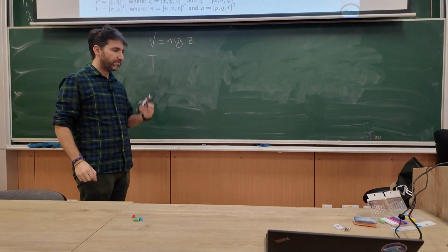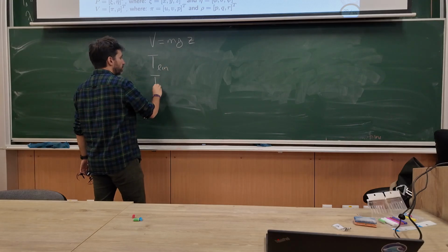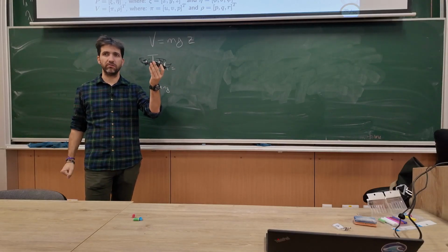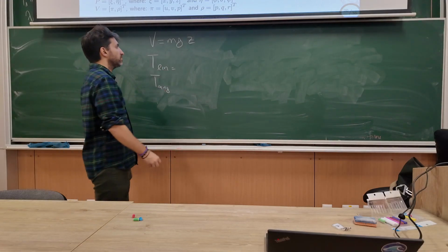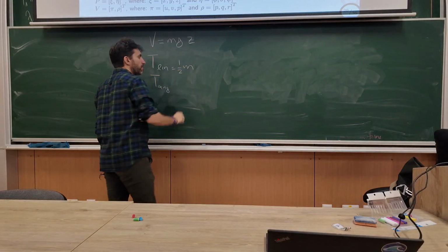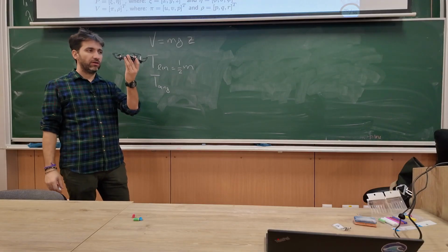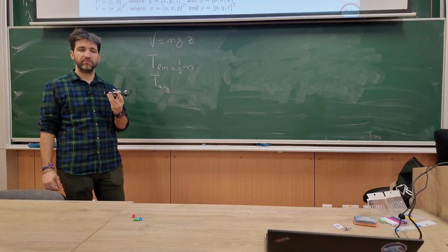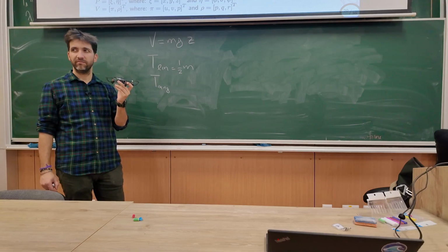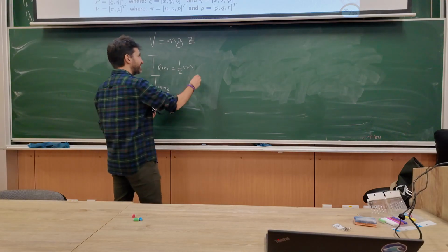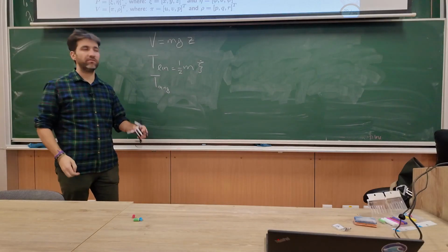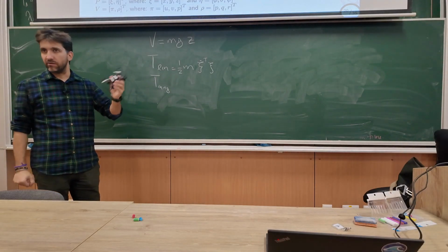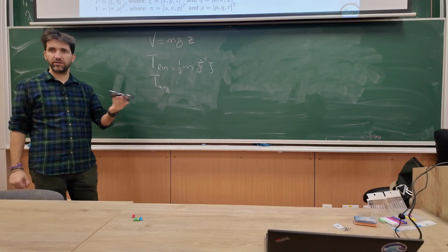Right. Kinetic energy. We'll split it in two parts, linear and angular. How would I describe the kinetic energy in the Earth frame for this one? One over 2 m v squared. So again, I have the mass. V: what was the velocity of the drone in the Earth frame? Not the velocities in the robot frame. The v is Xi dot, because Xi is position, so I take the derivative of Xi. And because Xi is a vector, I have to write it in this form, Xi dot transpose Xi dot, so I don't write a square. Any other linear velocity?